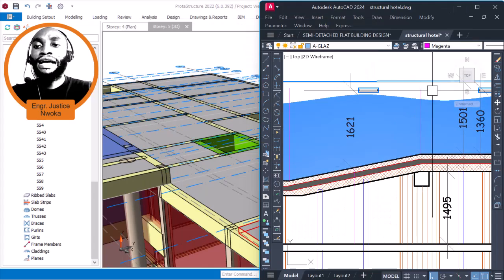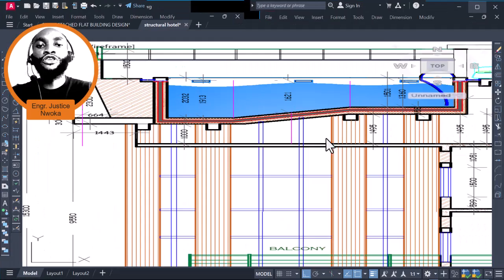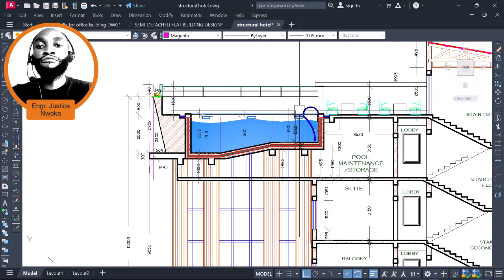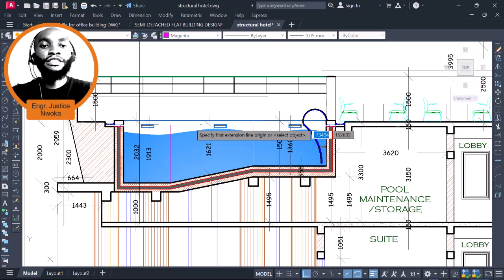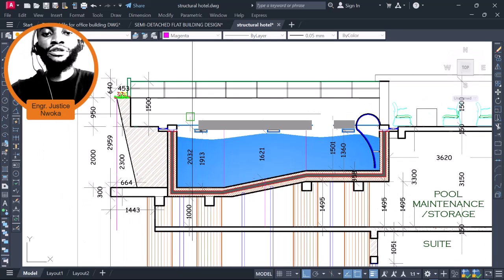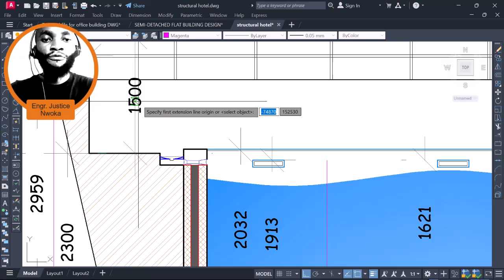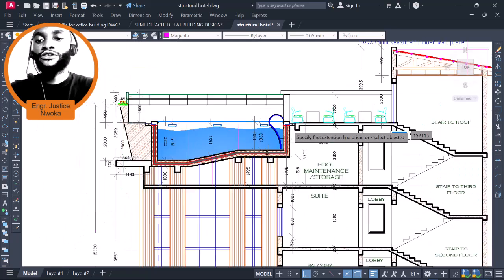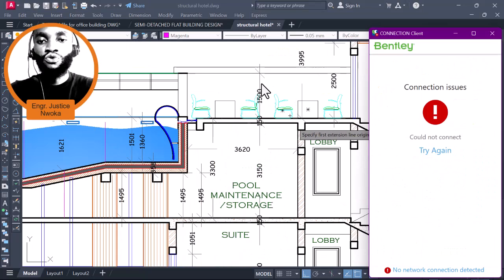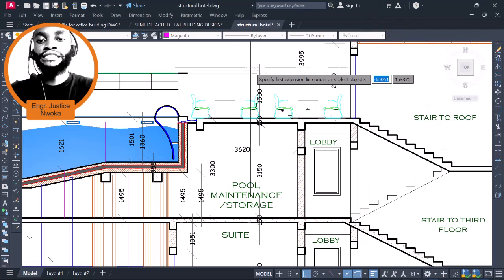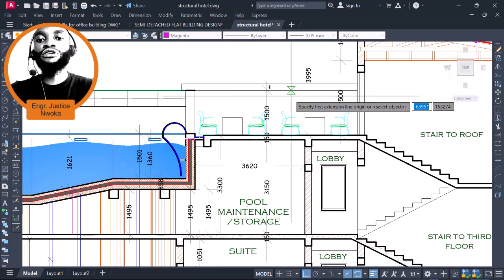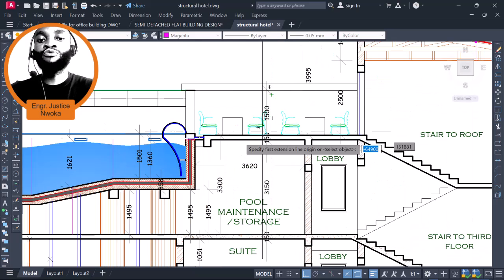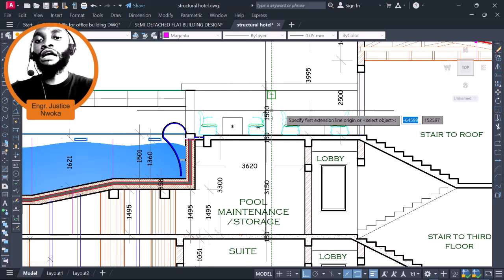Okay, so you can see how the CAD file is very important when you're doing your design. You must refer to it. Right now, clicking on this, you can see that we have a wall load of 1.5, and also a wall of 1.52. Basically we have a wall of 1.5 directly around the perimeter of that area. So we're going to do the parapet wall that is just covering the people sitting around the roof.